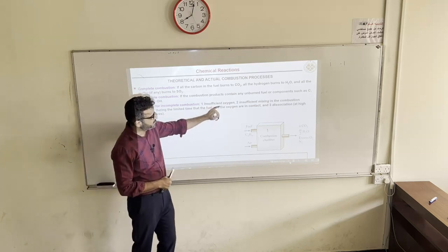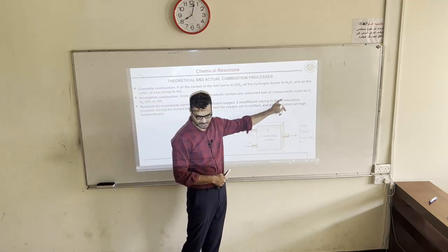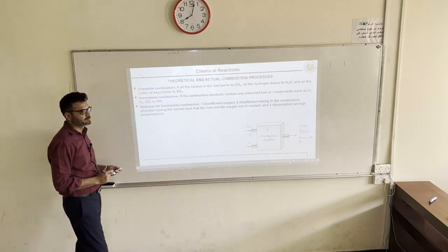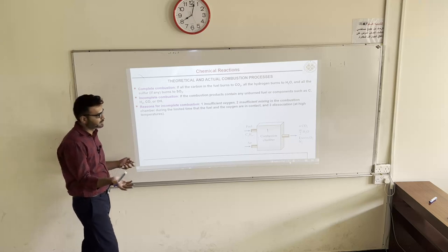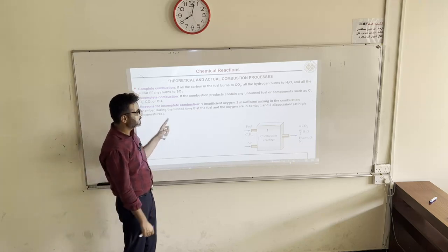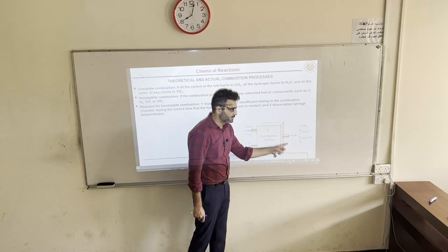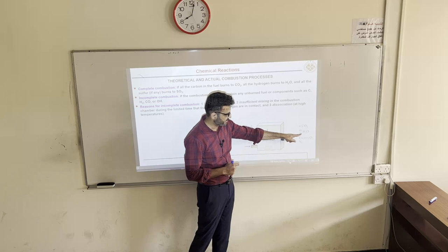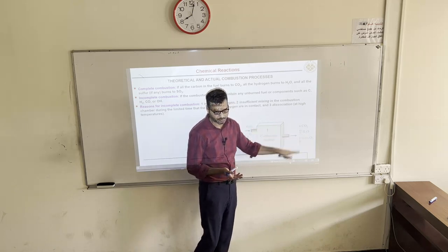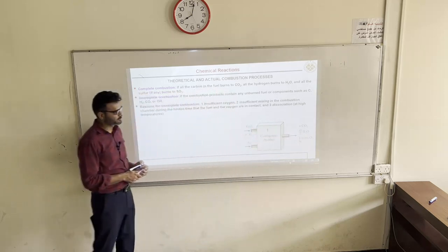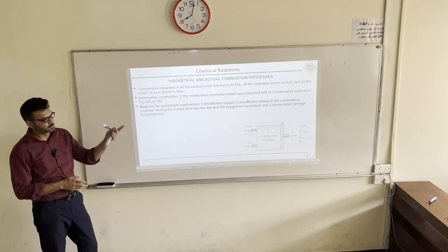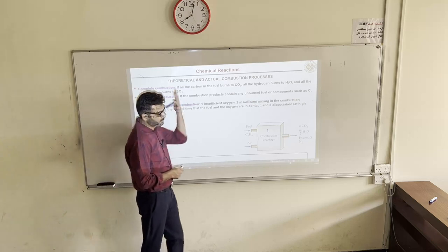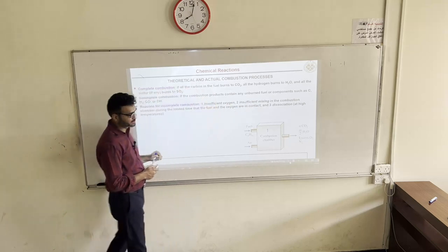Insufficient oxygen, insufficient mixing of fuel and air in the combustion chamber, or the ignition temperature not being achieved properly. Also, if the temperature during combustion becomes so high that it breaks H2O into H and O and so on, it will absorb heat, because some of those reactions are endothermic. So there are many reasons for incomplete combustion.